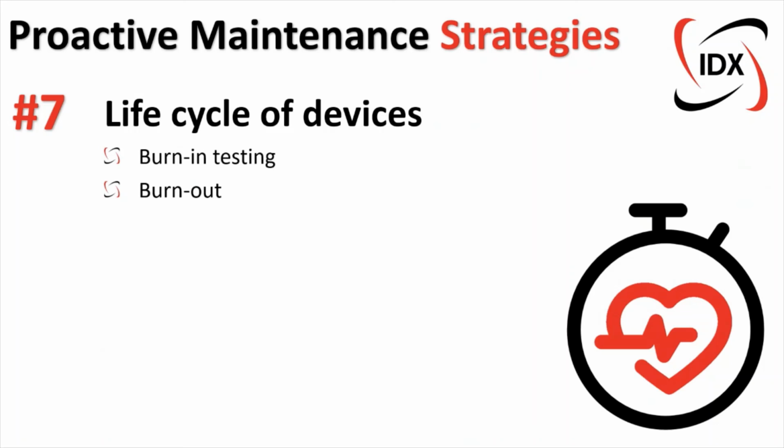Alternatively, you can do burn-in testing at your sites within your workshops. Connect the device you want to install in your network to a PLC within the workshop, let it run with a bus monitor attached to it for a couple of days, and make sure that the device does perform how it is supposed to. Prior to installing it, this will also make sure that you have the right settings in the device, such as the device address and configuration build.